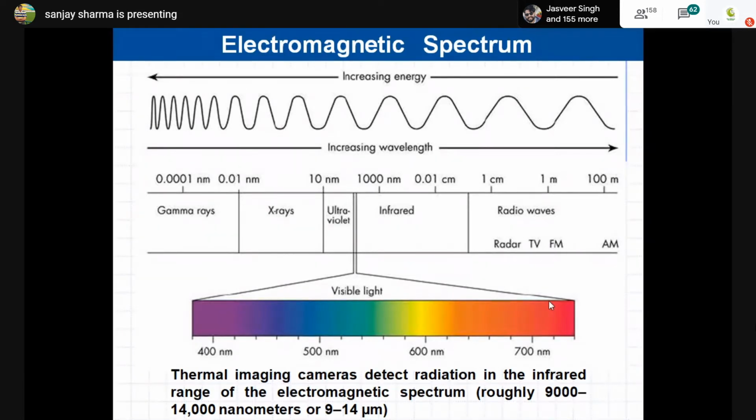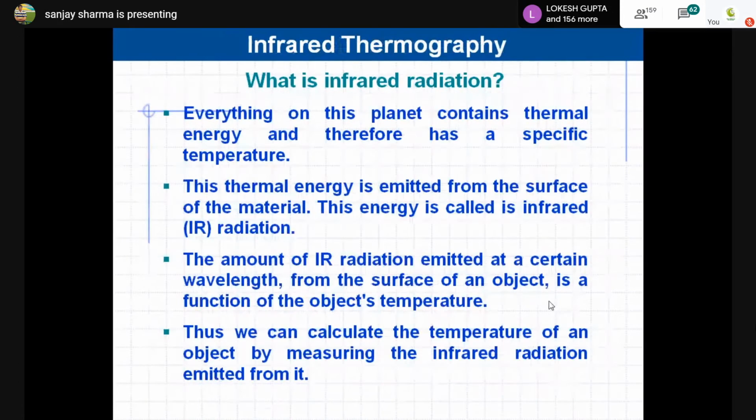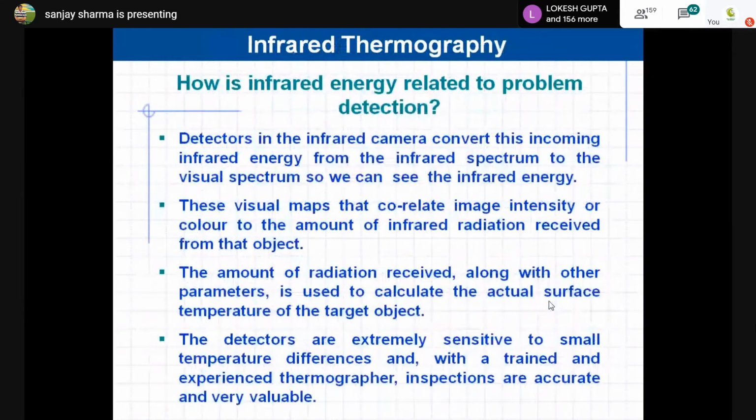It was located in Shimla, and it was a timber structure, so we used the thermal camera to find out the moisture content in the timber. There we could identify areas with higher moisture, moisture-affected timber, and those were replaced, and the building was rehabilitated using this. So this is what the infrared radiation technique is.